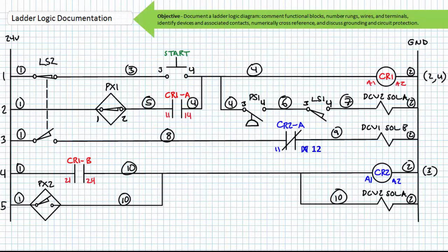Note that the mechanically interlocked limit switch 2 is being actuated into its activated condition. This can be made explicitly clear using the arrow convention. Similarly, note that the normally closed proximity switch PX2 is being actuated into its activated open condition. An arrow convention makes this explicitly clear. The normally closed terminals of the limit switch 2 being held open would therefore get terminals 1, 2, and the normally open terminals being held closed would get terminals 3, 4. Similarly, the normally closed terminals of PX2 being held open would receive terminal numbers 1, 2.